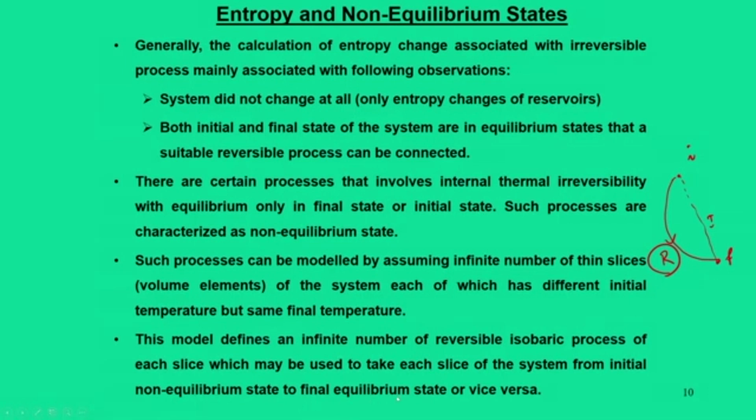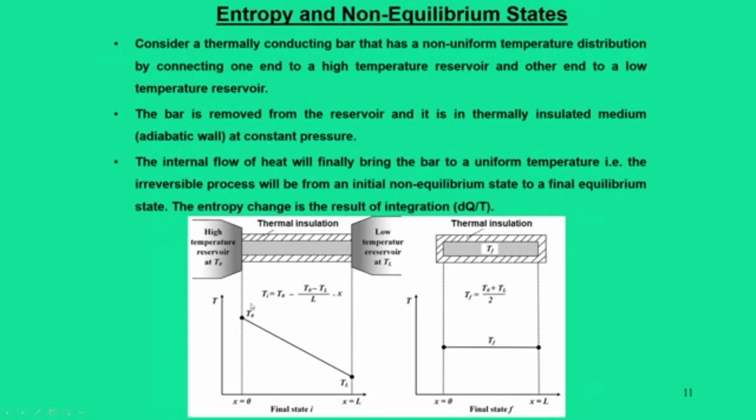So for the entropy change of the universe, delta S of the body is S2 minus S1, because the body goes from temperature T1 to temperature T2, and the refrigerator undergoes a cycle. Since the heat rejected is Q plus W, at T1, by clubbing all together, S2 minus S1 plus Q by T1 is greater than or equal to 0.